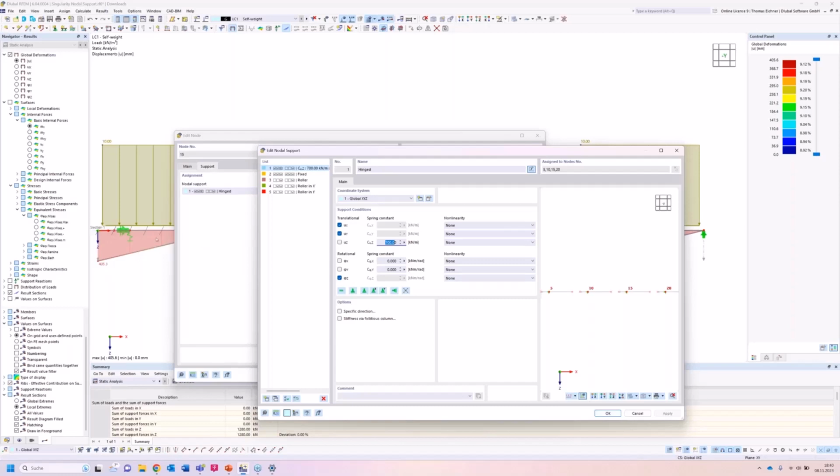For bigger systems where you have walls, and especially if you have a combined system of columns and walls, and you have modeled your columns as fixed, then you will have lots of singularities. So in practice, especially for reinforced concrete, for mid-size models, you would create two models.